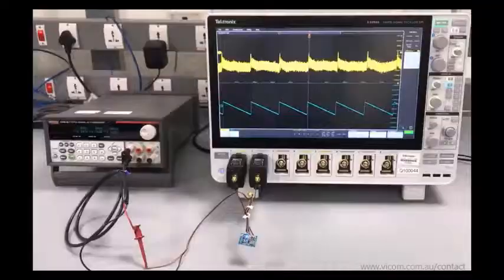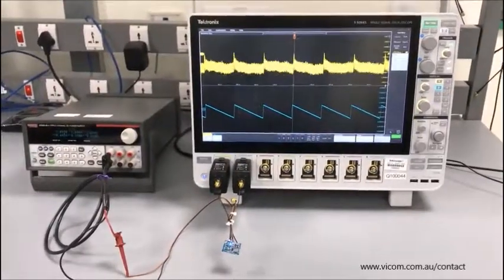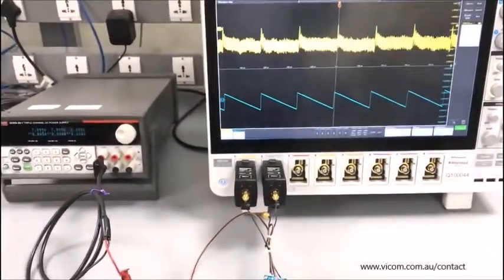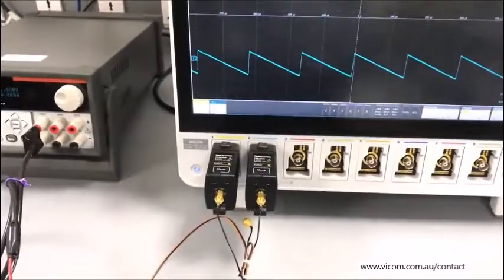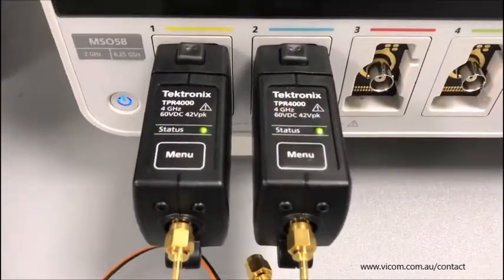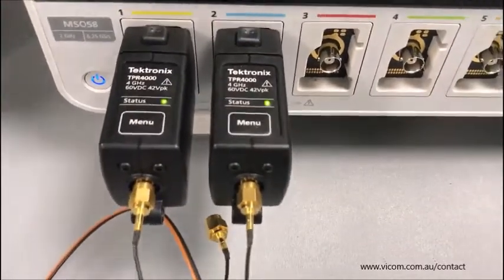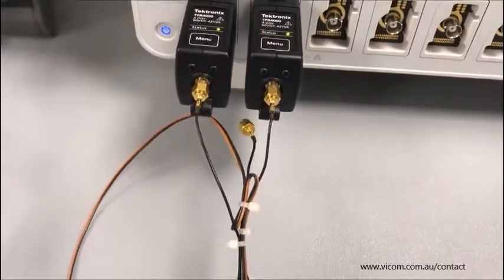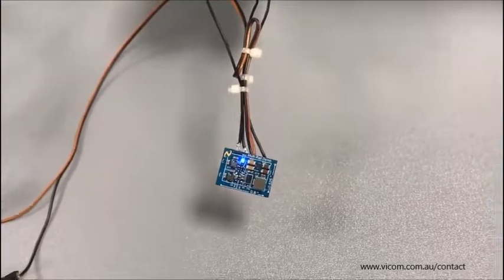Here we are looking at a multi-rail power rail DUT from Texas Instruments, and in the next few minutes you will see how the connections are made and how we can look at performing the power rail measurements. We have used this TI demo board which has got multiple power rails and connected to two power rail probes, in this case TPR 4000.